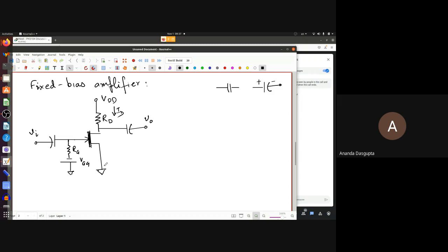Okay, the whole idea, I see from some questions that I get, people are still a bit confused, or may have forgotten about what AC analysis really means. Your voltages and currents are actually sums of the DC value plus the AC values which come in because of the signals. The DC value or the average value we have already analyzed.